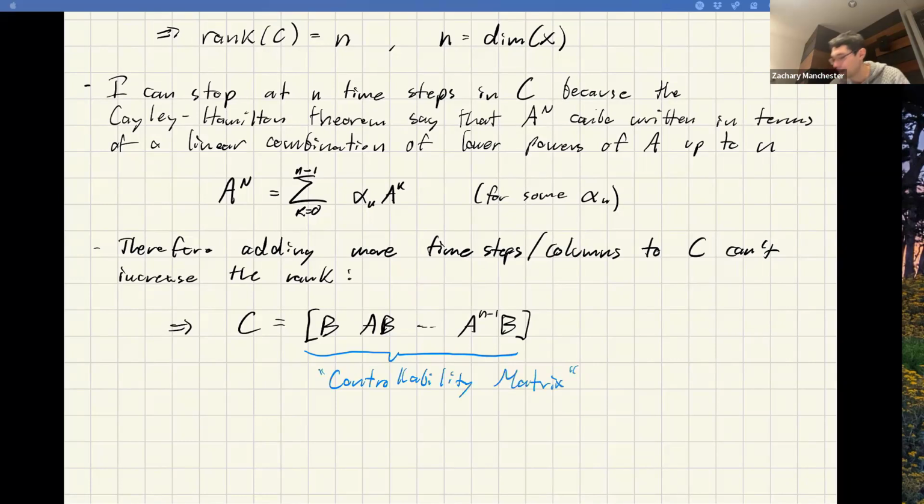Now we have this nice general theory for LQR. If I give you a linear system, or you linearize some nonlinear system, and you want to develop a controller for it, write down some Q's and R's that are positive definite, and then check this thing. If it has rank n, the system's controllable, good to go.